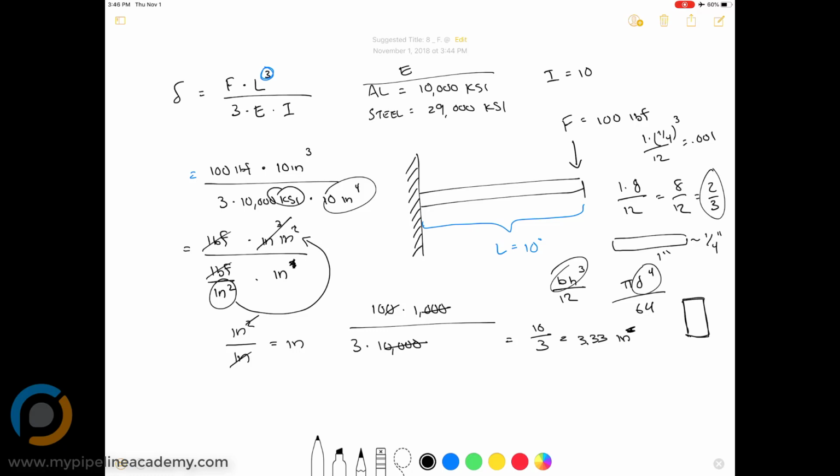And, you know, oftentimes you have a max deflection in mind that you want to stay within. Maybe you want to make sure that you don't go past half an inch of deflection for whatever reason. So you want to adjust your base or your height or your length so that you're less than half an inch of deflection. And if you have to go through by hand like this and do that every time, it's cumbersome, it's prone to errors, right? Just doing math by hand is not efficient, and it's risky because you might make a mistake somewhere.